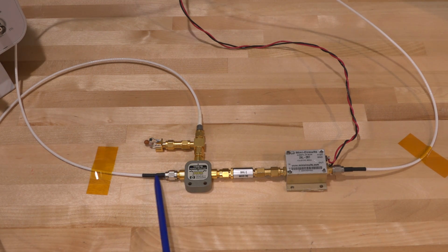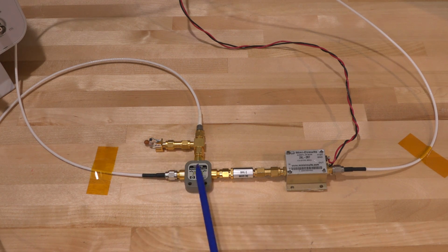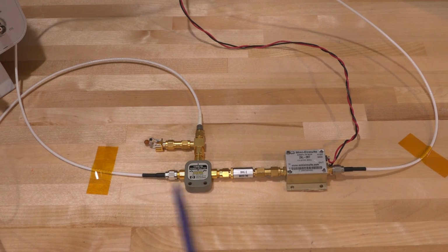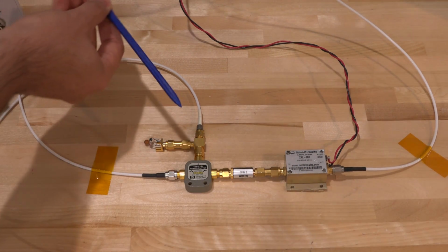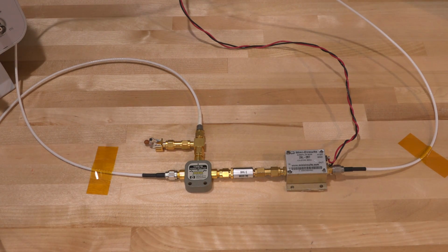and the reason I'm using this is because it allows me to connect one side to the oscilloscope, and this directly goes into the MSO5 series oscilloscope, and the other side we have an attenuator followed by just a regular amplifier from Mini-Circuits. The output of the amplifier I'm also looking at on the oscilloscope. The reason I'm putting all this over here is because the impedance looking into here at very, very low frequencies is going to be 50 ohms, which is going to match perfectly to the impedance of the source itself.